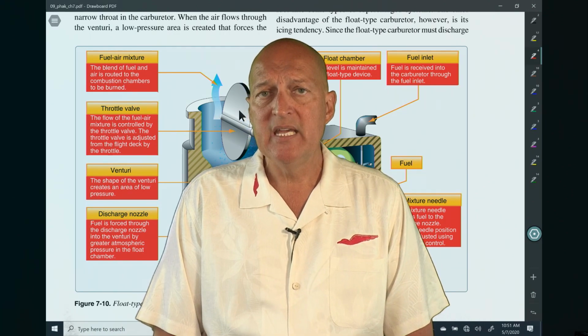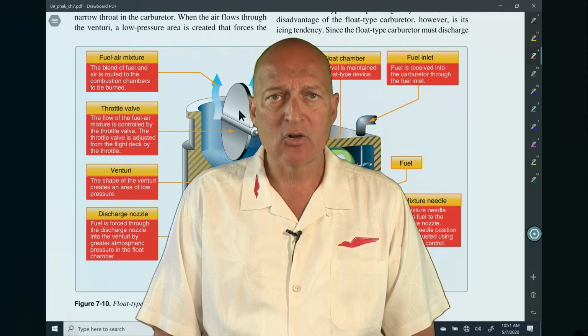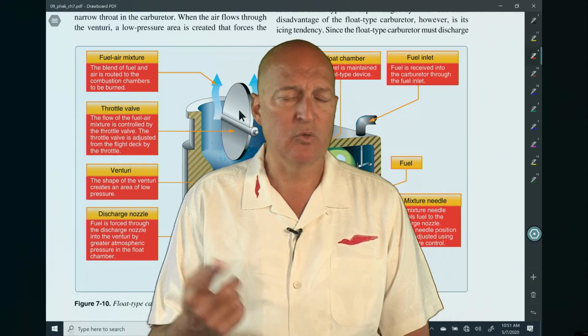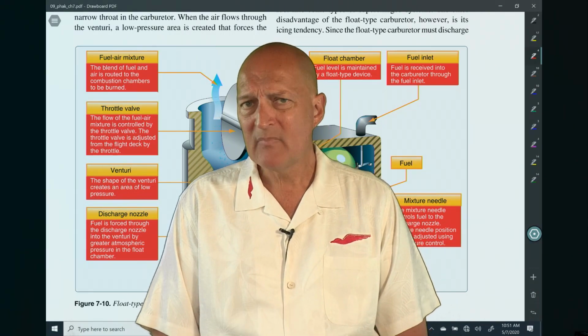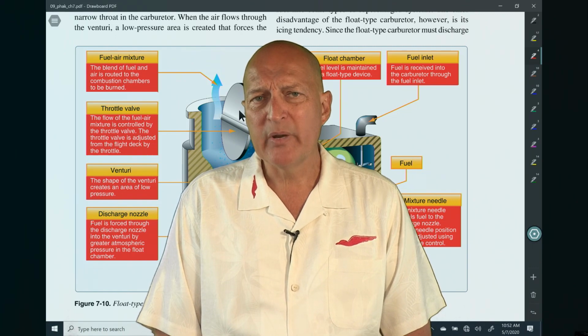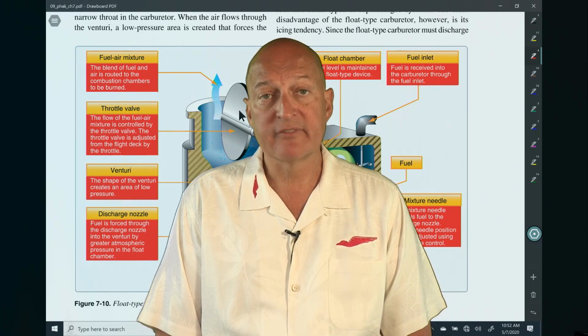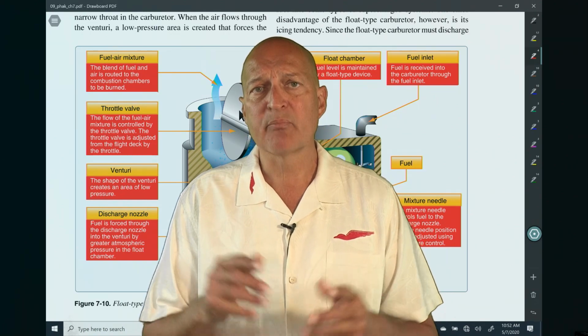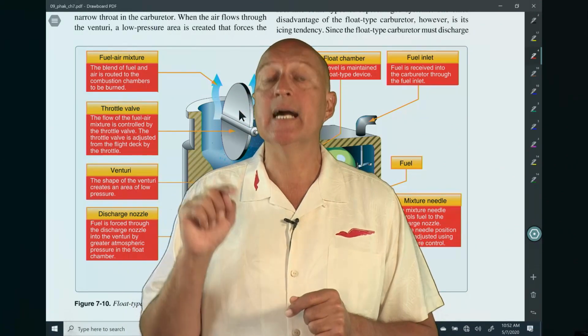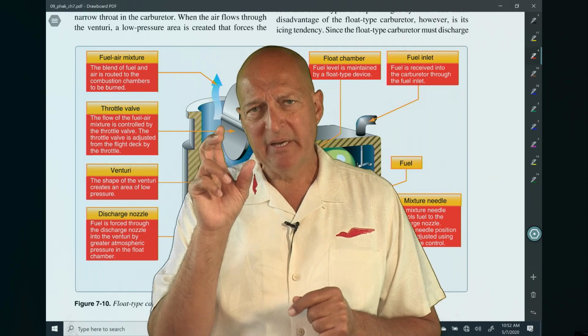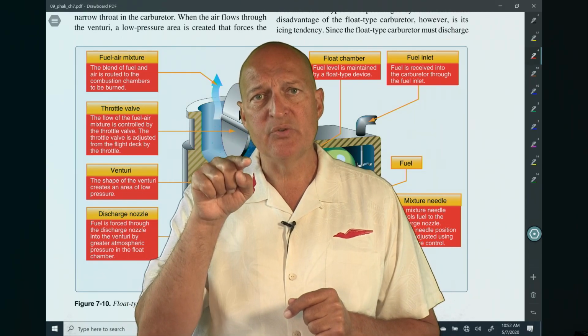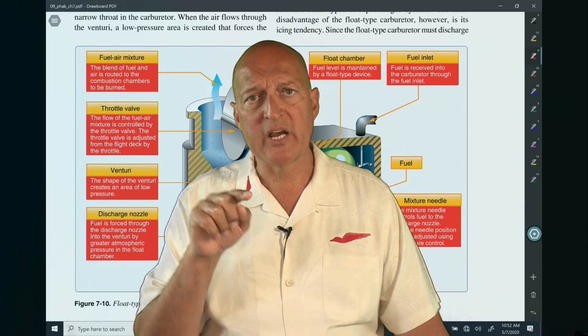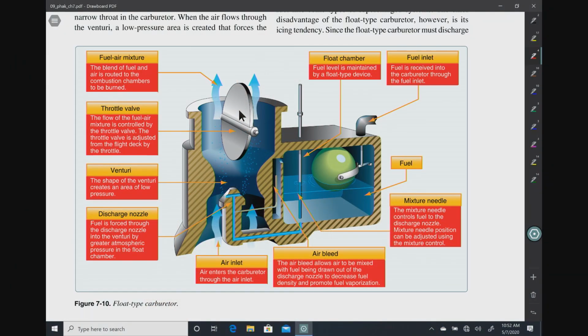One of the reasons being is that with more modern aircraft, they use fuel injection, which we'll talk about in just a second. But the other thing is that carbureted engines, even though we flew them for a long time, can be a little finicky when it comes to icing up, because the butterfly valves and that inlet that you see here in this particular configuration, at various different temperatures, even temperatures a lot warmer than you might think, can actually ice up.